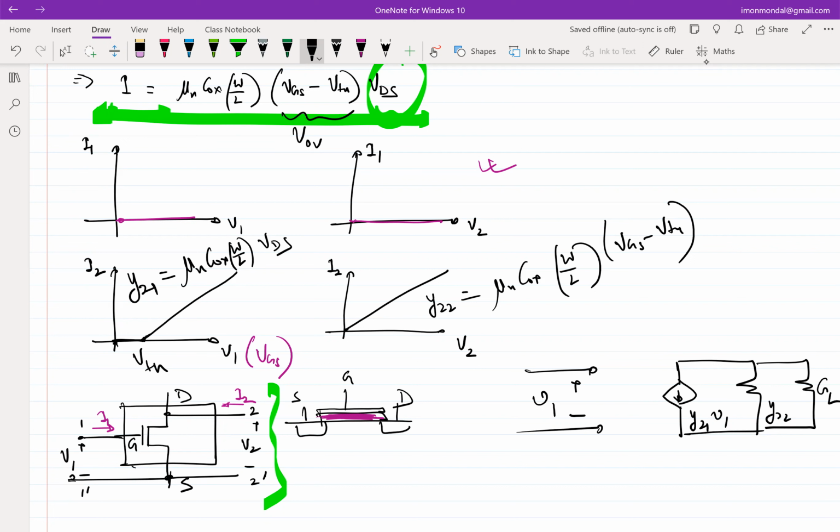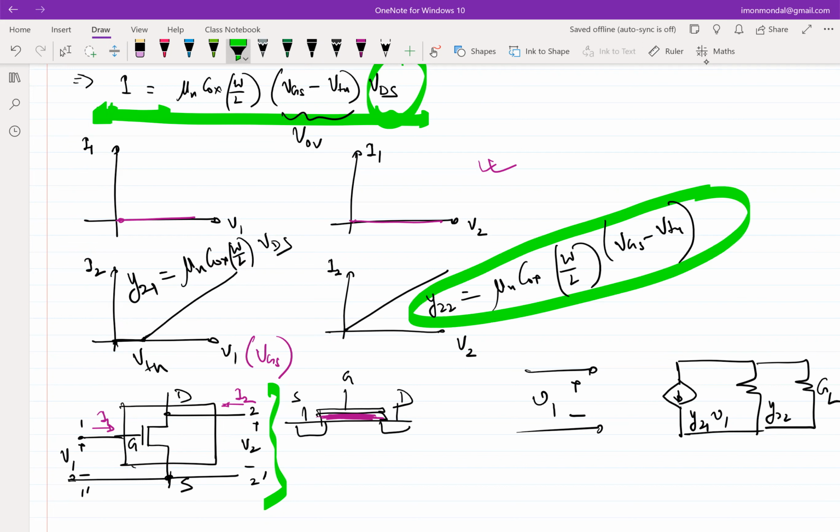So the internal characteristics of the device are generating a Y22, right? This is not a physical resistor. We are getting a Y22 because the device has a certain structure, a certain way of operation. Because of this, Y22 is not 0. Which means that under the condition that we are looking at, this device cannot be used as an amplifier. Make sense? But note that this device can be used as a resistor.